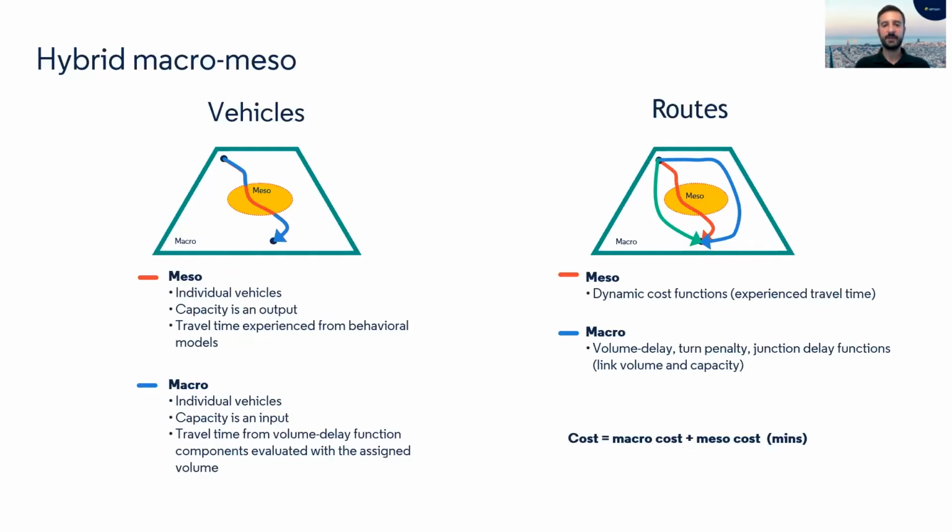First, it covers the need to build larger models without having to extend the meso model. This automatically means less computational and calibration efforts on the dynamic side, but we can still use the macro model, which is simplified in terms of geometry and path calculation. Second, we can reduce the size of the existing meso model to meet the performance simulation metrics. This means that we will focus only on the study area, but without excluding the rerouting phenomenon.